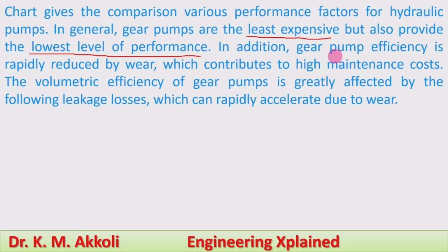In addition, gear pump efficiency is rapidly reduced by wear after using for a particular time period, which contributes to high maintenance cost. The volumetric efficiency of gear pumps is greatly affected by leakage losses, which can rapidly accelerate due to wear. Those leakage losses will reduce the volumetric efficiency.